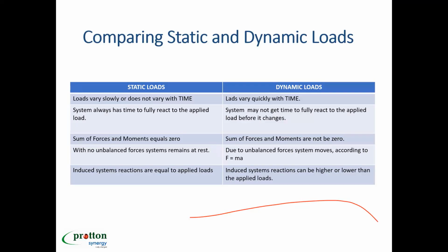In the static case, the system always has time to fully react to the applied load. It means that with thermal load, if you check, the temperature is changing slowly. The system is having time. It is not responding very quickly. So it's not a hammer effect which is happening. The system is getting time, what you can call quasi-static. In dynamic, what happens? The system doesn't get time.